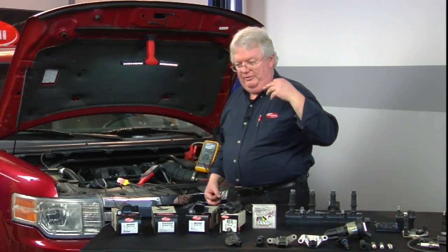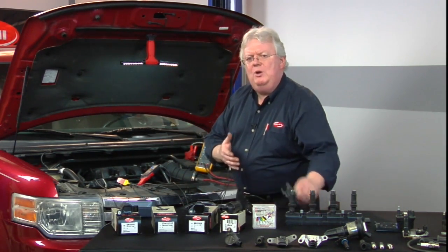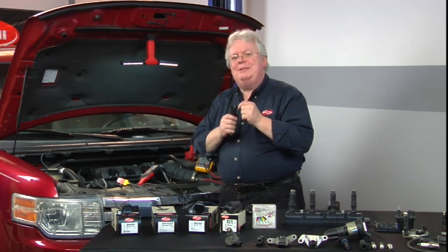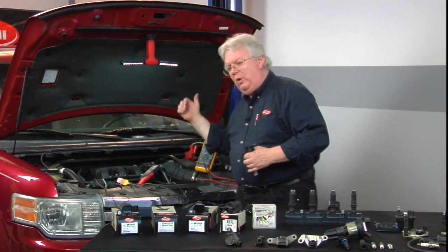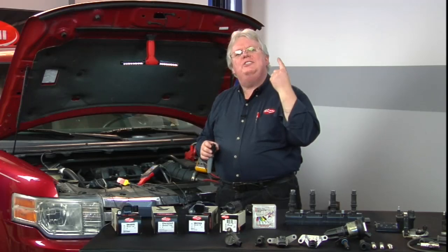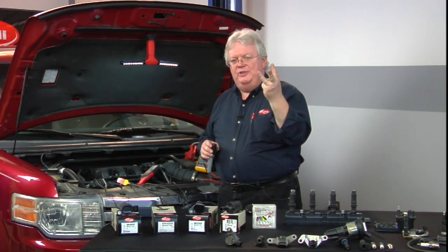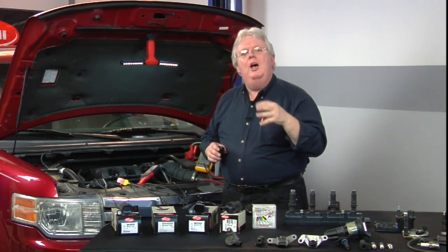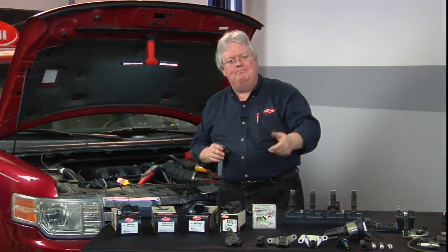So that gives us two or three things. We're getting a pulse from the ignition coil. We've got a good primary winding for both power and the ground from the PCM when it's applied. So really, one connection with your voltmeter into the coil-on-plug at the right spot, at the side the PCM supplies the ground, checks the fuse, checks the coil winding for continuity, and when you start the engine, checks the coil driver in the PCM. Three things checked, one spot to hook your meter. Hopefully, if you're not doing it that way, you will, because that can save some time.